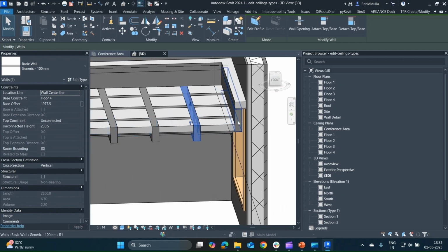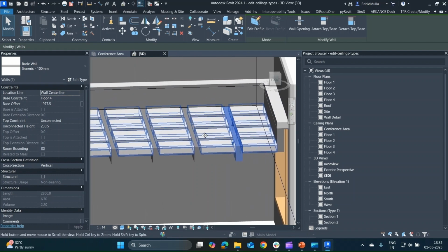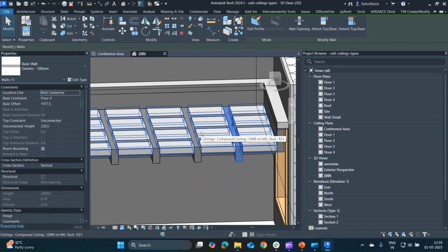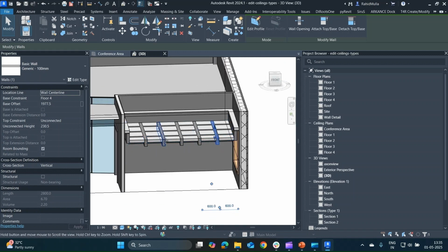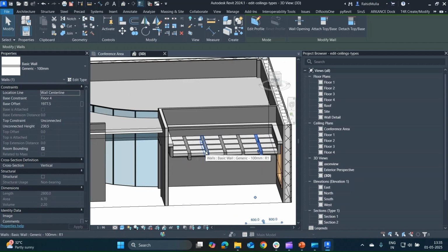So again, you can model suspended ceiling, and if you have vendor details here, there will be shadow gaps, as well as main rods which will be suspended from a ceiling, and then there will be main channels which will run all around, which will hold the panels. There are different types of ceilings, such as sandwich panel system, as well as suspended ceiling, and then there is a metal grid ceiling. I have also created a family.